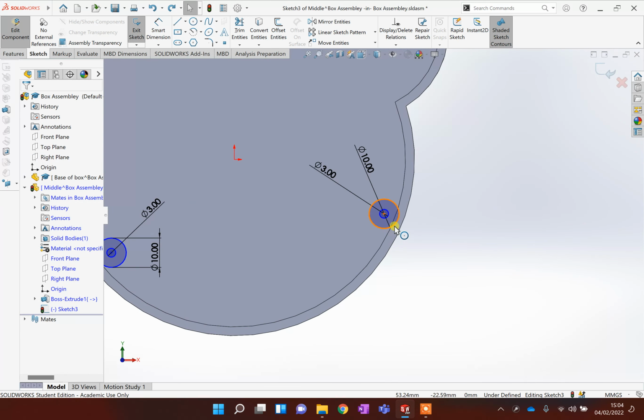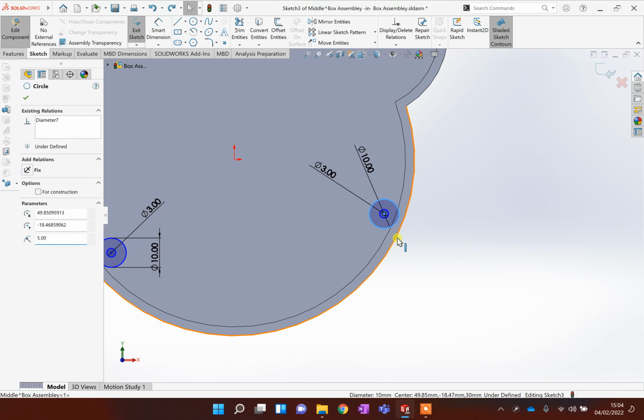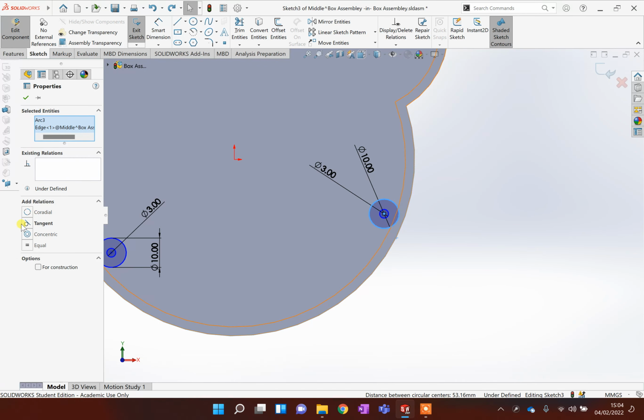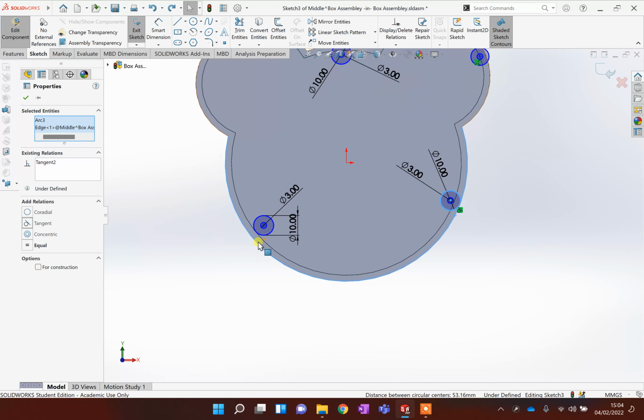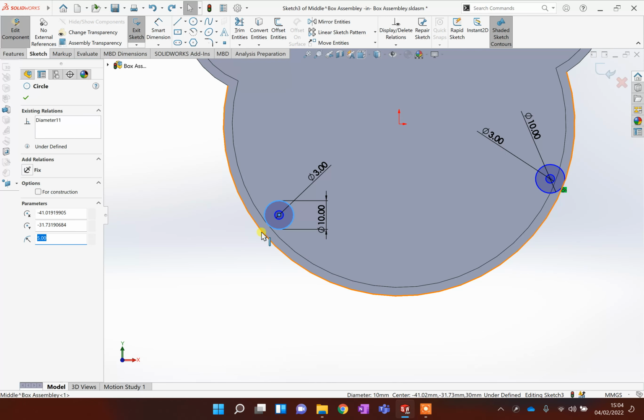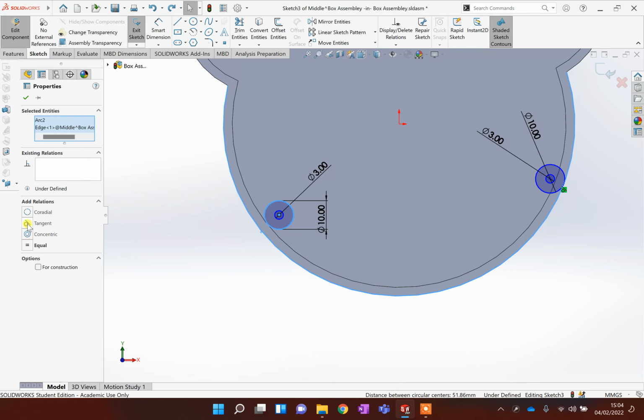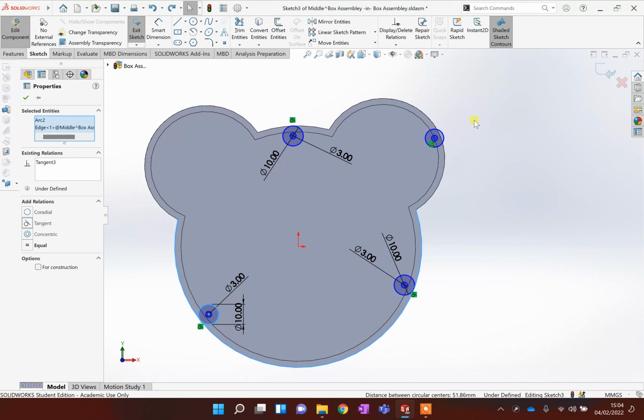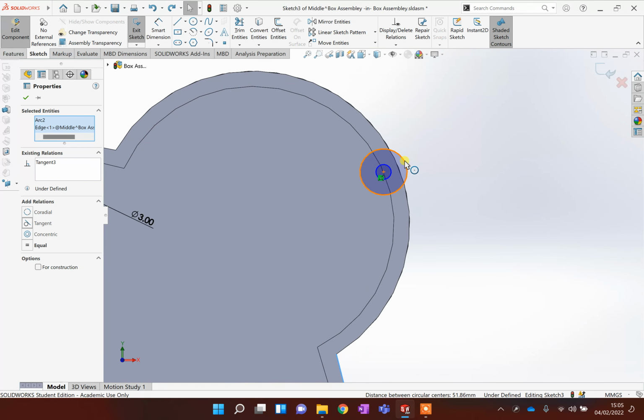Okay, you'll see where this is going, I promise. So that and the outside of the circle. Choose tangent over here. This is just going to make sure they all are the same spacing from the edge of our box. They look nice and neat. Tangent, there we go.